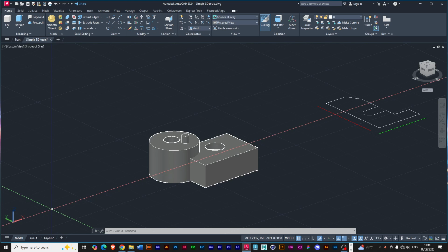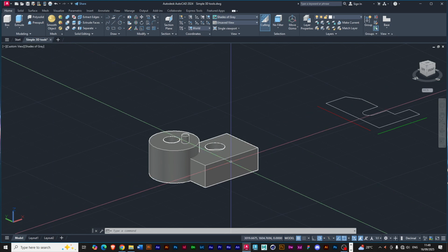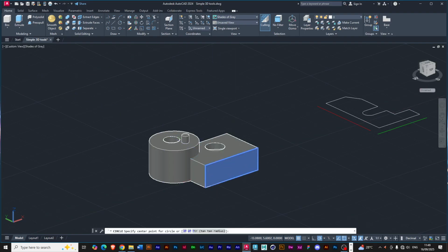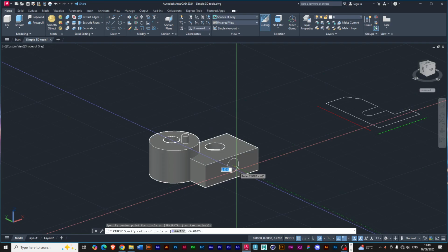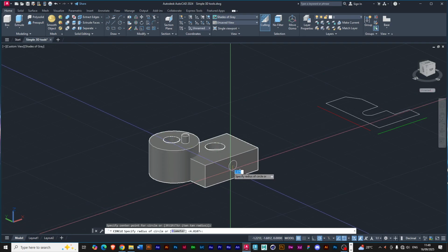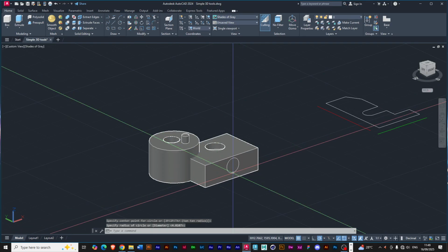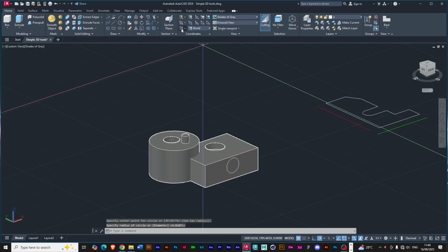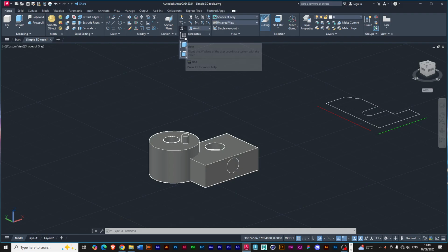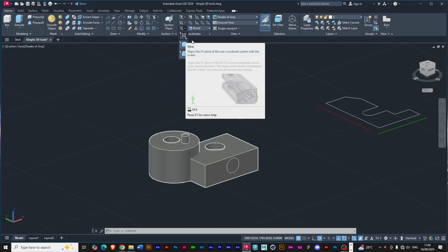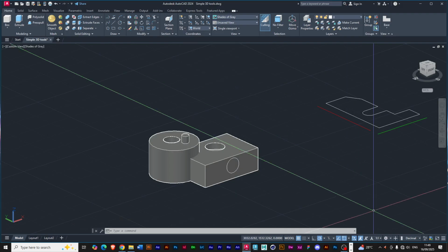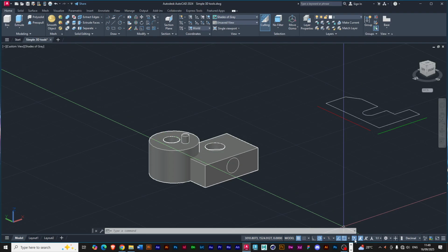No matter what you are drawing, it will only draw it on the Z plane. So if I want to draw a circle on this guy and I pick my circle here and I click to drag, it's not going to draw based on that until I trigger something, this thing we did yesterday, that's view plane, or I trigger on my dynamic UCS here, this one that we added.